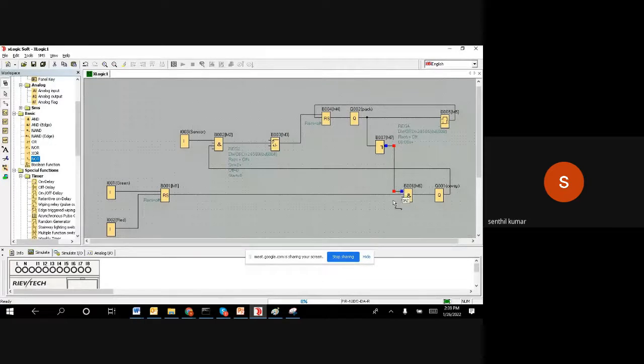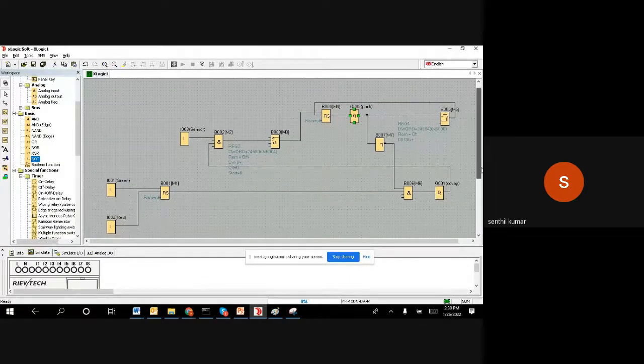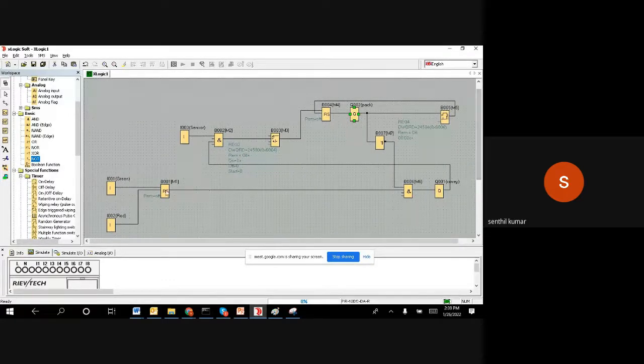So what I'm trying to achieve here is when this packing motor is running 1, then it gives a 0, it comes a 0 and it stops the motor. Whenever the packing motor is on, we want to stop the motor. That is the intention. When the packing motor goes off, if my system is running, then it can allow it to run, right? So this is a very preliminary logic that I made, but still I'm not sure whether I have implemented everything.